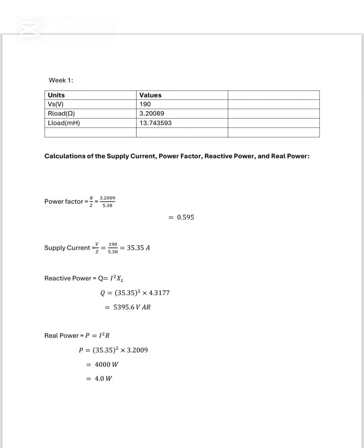The problem is wasted energy, such as reactive power. Many industrial machines, such as motors and pumps, pull reactive power from the grid to create magnetic fields. This power doesn't do real work, but takes up space in the wire. The measure of this is the power factor. This is a measure of efficiency.